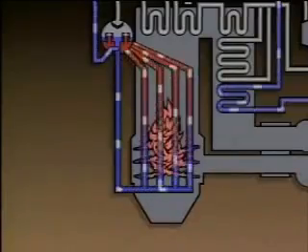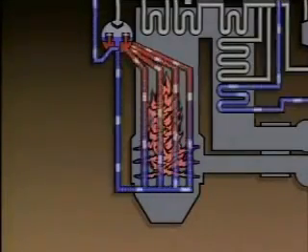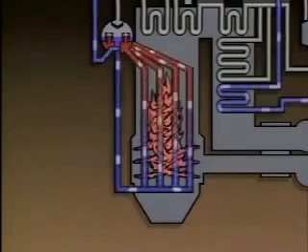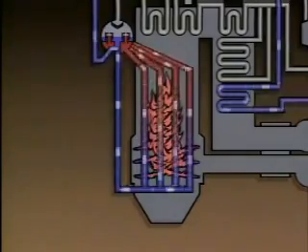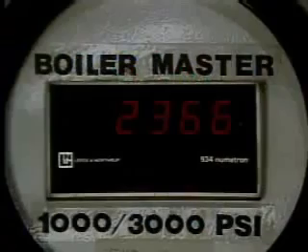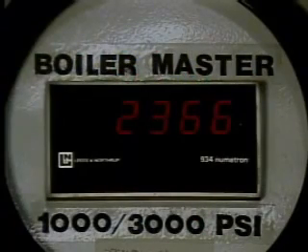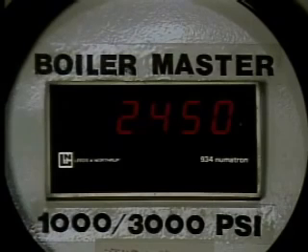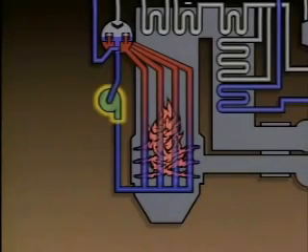Natural circulation of water in a boiler is affected by 2 factors. They are the amount of heat produced in the boiler furnace and the pressure at which the boiler operates. For example, raising the temperature in the boiler furnace increases natural water circulation because it results in a greater temperature difference between the water walls and the downcomers. Increasing the second factor, pressure, has a negative effect on natural circulation because as pressure increases, the density difference between water and steam decreases. In some boilers, boiler water circulation pumps are used to increase circulation.